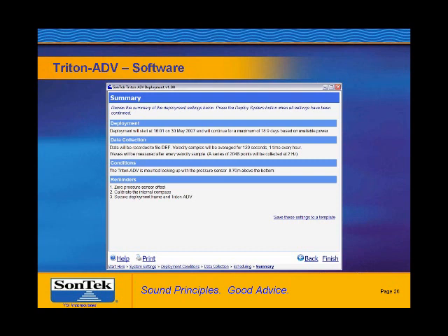Well, Mike, the answer to that is the typical depths are in the range of 10 to 20 meters below the still water line. But they can be deployed as deep as 60 meters. That's the actual maximum limit for the Triton. Now, of course, the deeper that you install the system, because it's a pressure-based system, the longer the wave periods that you're going to be limited to.